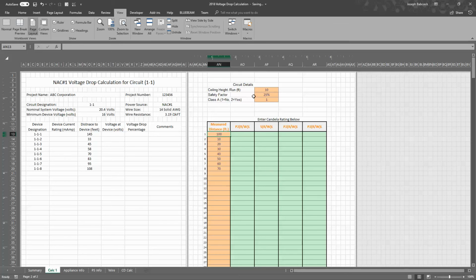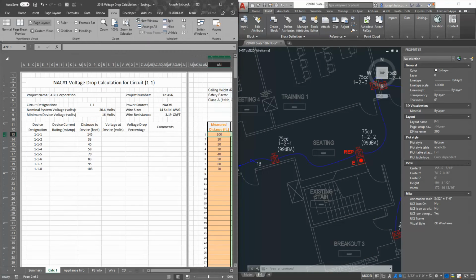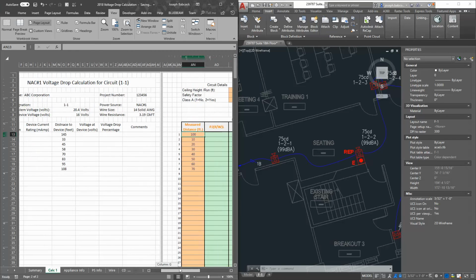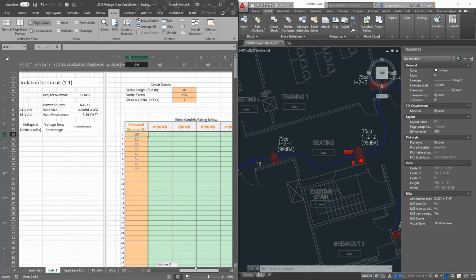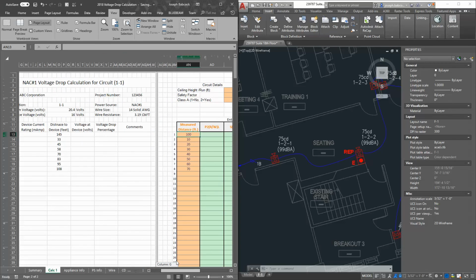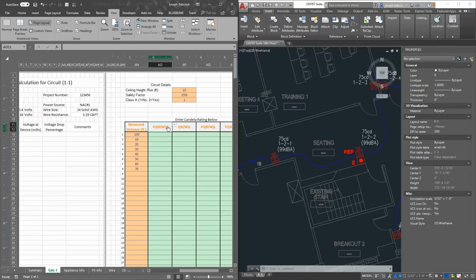So from there, I'd like to show you my idea of now having only 2 references open while we're doing voltage drop calculations. I've created some drop-down lists here that have some notification devices, not all of them, but the System Sensor and the Wheelock ones. So I'll show we can select the P2RL and the SRL strobes.